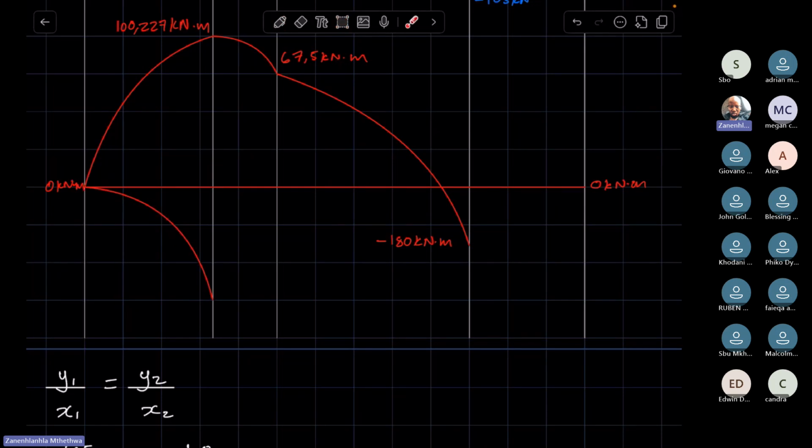How we represent the bending moment below the 0 line is we take the convex approach, meaning that when the bending moment is decreasing, this is how you show that the line is parabolic, but taking a convex as opposed to a concave shape.